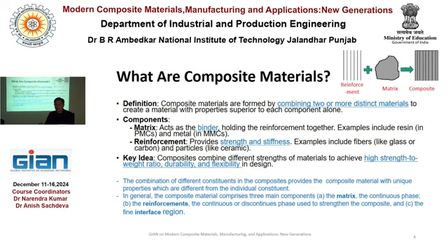That means durability will be seriously influenced by the interface characteristic. The interface characteristic will mostly be influenced by the manufacturing process. So good manufacturing means taking good care of the interface. That is very important for final composite material quality.